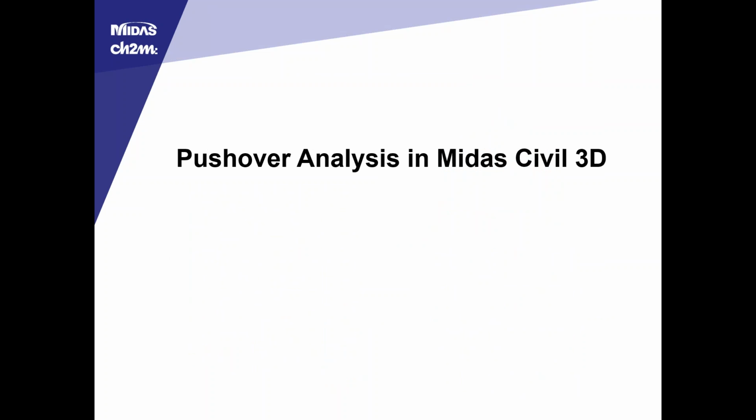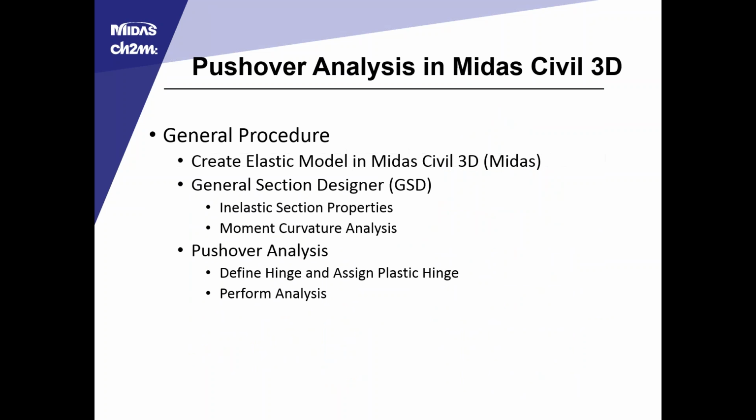So with that, we'll move into the pushover analysis within the program. The general procedure within Midas Civil 3D is to create the elastic model in Midas Civil in the main program, then move to the general section designer, calculate the inelastic section properties, calculate the moment curvature, then move back into Midas Civil 3D and define the hinge, assign the plastic hinge to the hinging element, and perform the analysis.